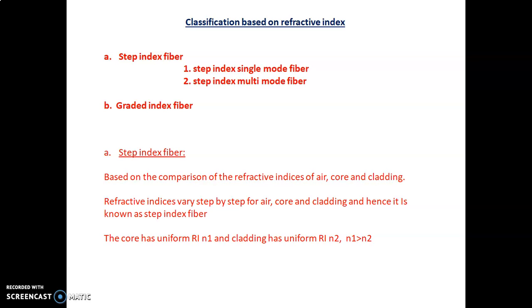And this is according to the classification of refractive index. You know what is meant by refractive index. Speed of light in vacuum divided by speed of light in that particular medium, that is known as refractive index. So based on the refractive index, optical fibers are classified into step index fiber and graded index fiber.